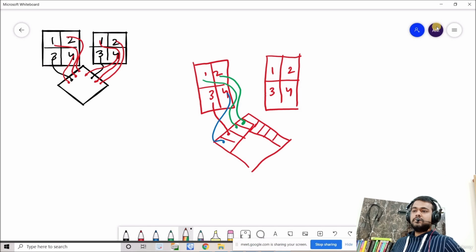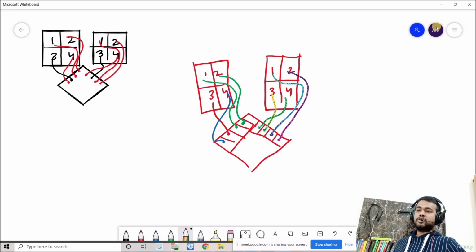So third is connected to here, fourth is here, this one is here, and all the byte groups, whatever pads we are using for LPDDR4, for each byte, all are on this particular section. So you can't say we have some pads in this section or here; those are properly defined, and from the SoC side everything is fine. So we have to do the layout accordingly. Here I'm not talking about any particular pad, I'm talking about the whole byte group that we have discussed, right?